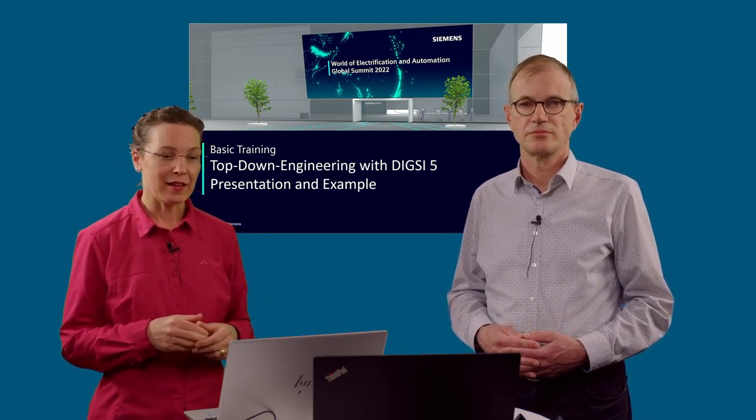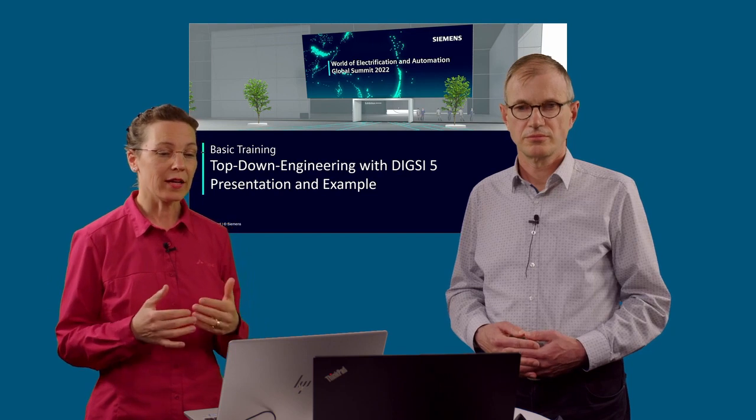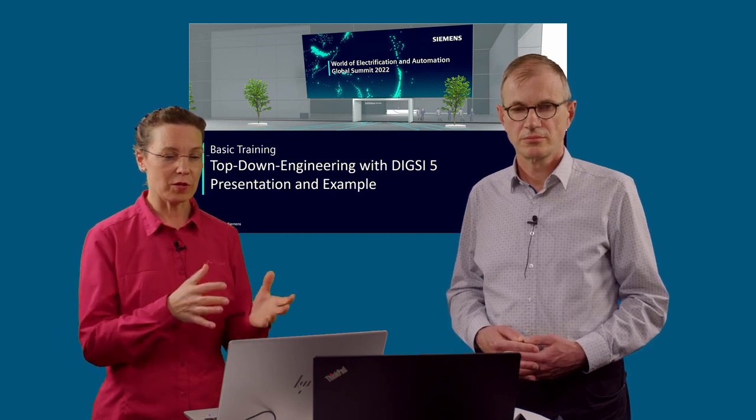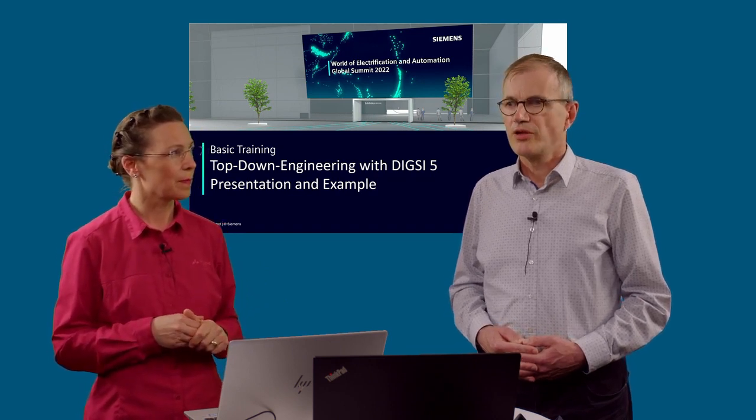Okay, thanks. And then it's a question, I think it's from the device, more from the cProtect view. Why can't we download the configuration from the device, edit it as required, and then upload it back to the device? Why is the limit to the original project file only? This functionality we have added last year in DIGSI. This is something, it has nothing to do, from my understanding, with the topic I presented today, but I know this was a long requested functionality, and this is possible with the version I think we released last summer. We can do it. It's a project merge. Look into the DIGSI manual and look for project merge, and then you will find it.